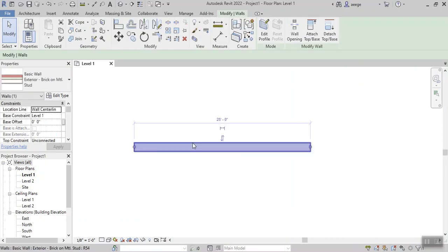When you click on this wall, you selected the wall, and on the left side, the properties bar shows you the basic wall, its exterior wall, and so on, the total length of which is 25 feet. You also see two arrows in opposite directions, up and down. Those arrows indicate where the exterior side of the wall is. If you click on it, exterior becomes down below. That double arrow basically indicates where the outside of the wall is. Just keep that in mind, all right?